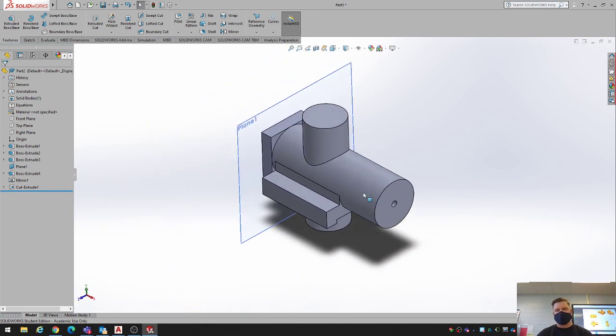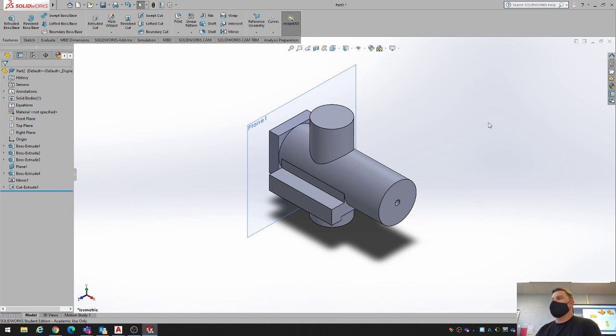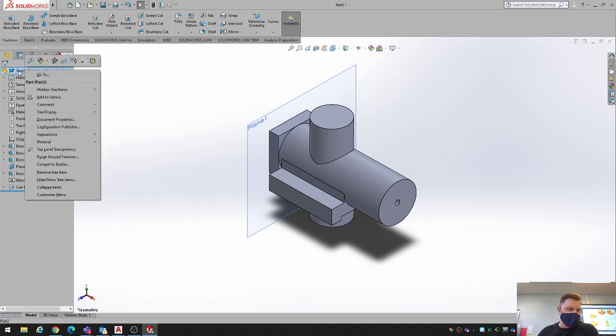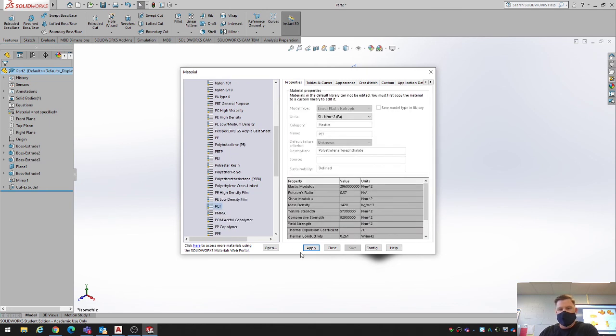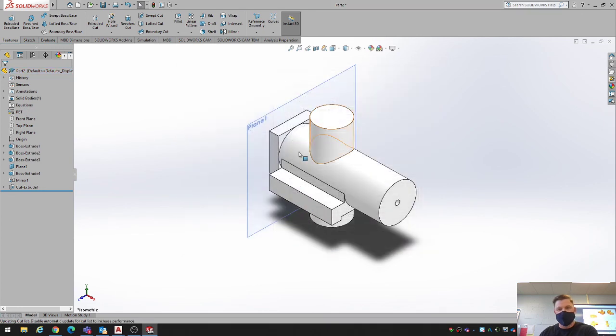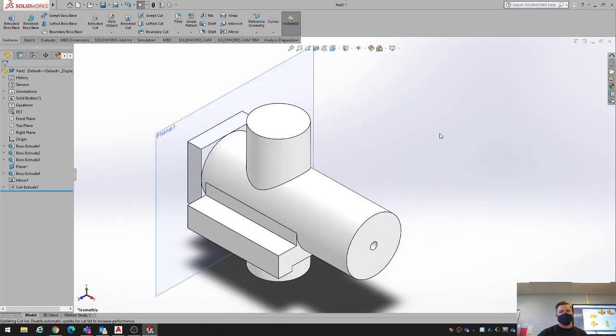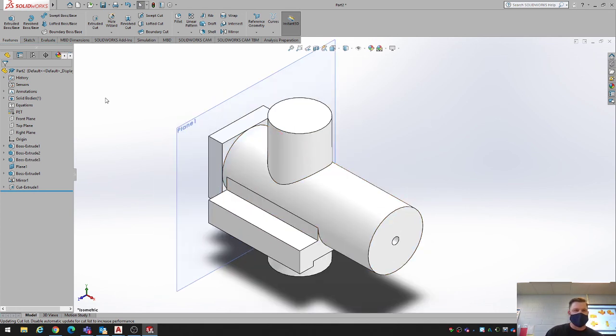All right, here's how we're going to check this. On the upper left corner of your worksheet, it says material is PET. So we're going to right click on part 2 up at the top. Once you're done, you're going to go to material, edit material. Under plastics, there's a material called PET somewhere. I know my alphabet, I swear. A, B, C, PET. We're going to hit apply and then close. That basically made it so the density of the object is made out of plastic. It's kind of like a way of simulating things.